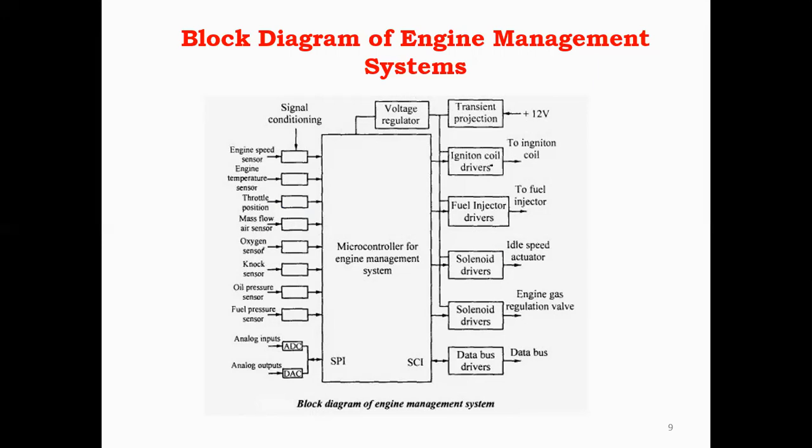This is the concept of the engine management system. Here we have input and output devices, a processor, and other devices, as well as onboard diagnostics. Onboard diagnostics will define what errors are produced in the engine, and these will be diagnosed by the automatic system. For example, if the temperature increases in the car, the system automatically reduces the temperature by increasing the cooler value.